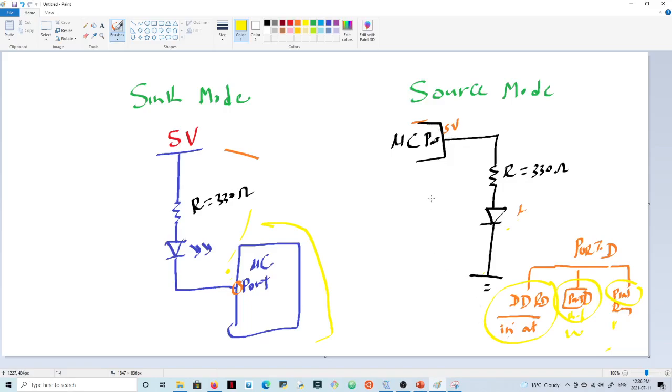All right. Now, one more thing you need to understand. When you talk about the microcontroller, you have ports. If you think about the AVR, I'm going to deal here with port D. So you will have registers connected to a port. The first register is the data direction register. So in this case, the data direction register of port D. You will have the port register, and you will have the pin register.